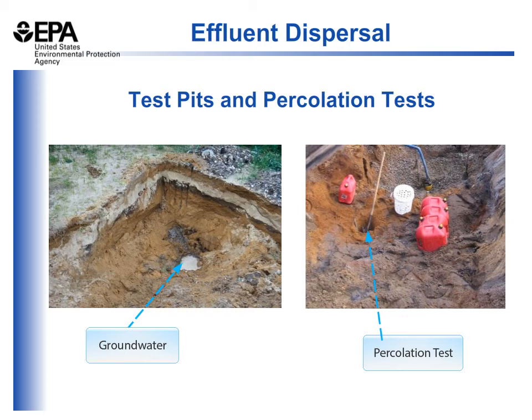In very tight soils, the percolation rate can be quite low, such that the water in the test pit is falling at a rate of 1 inch over 30 to 40 minutes. In very permeable soils, such as a coarse sand, the infiltration rate may be faster, and is often measured in these soils at a rate of 2 minutes per 1 inch of fall.